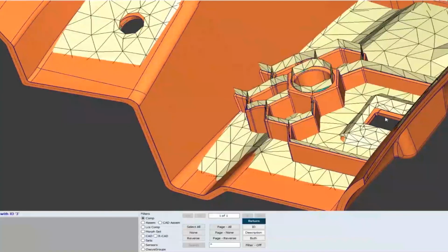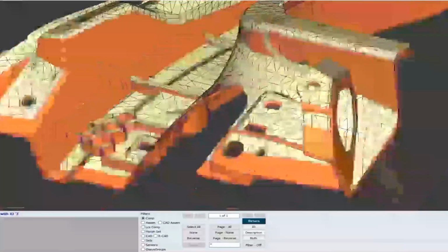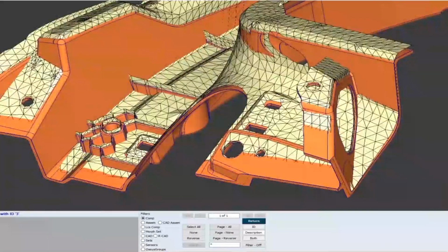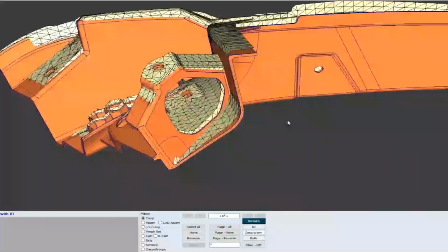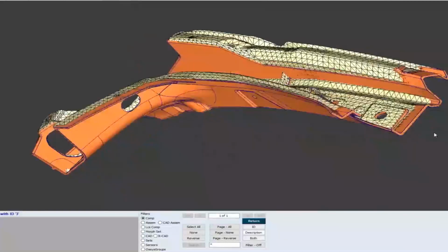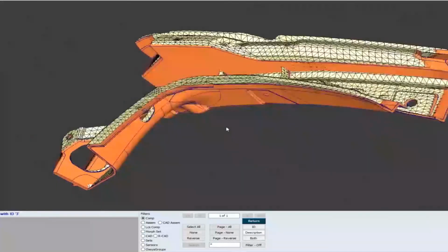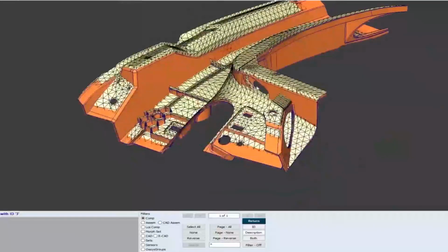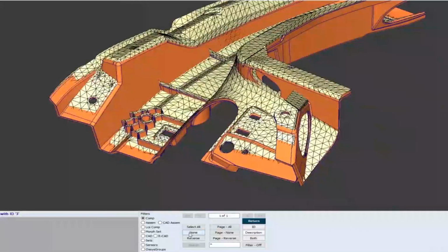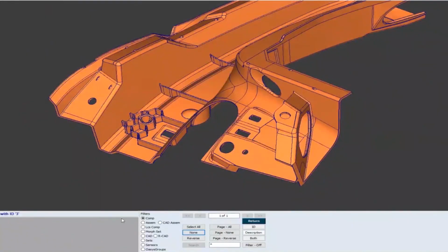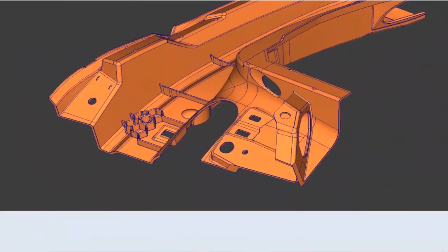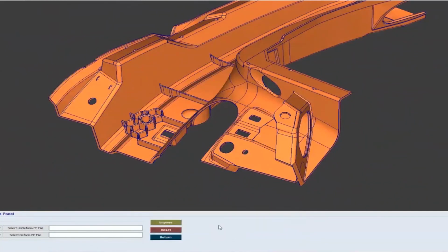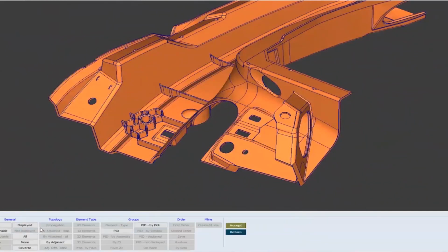This would be the warpage corrected mesh, which we can export from the previous window. I can zoom, I can just rotate the model just to show the complete model. So if we have the nominal mesh, nominal CAD, and the warpage corrected mesh or the warpage compensated mesh, then we can go in CAD Morphing. We have a nice tool that is called an imposed deformation, where I need to select the CAD.